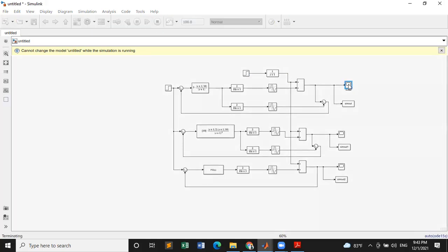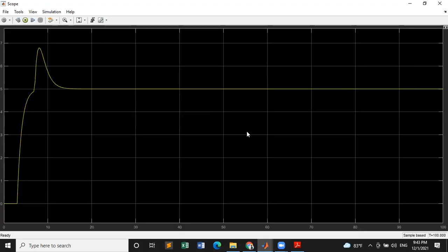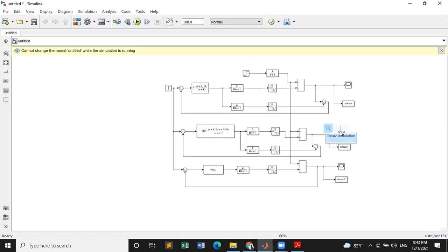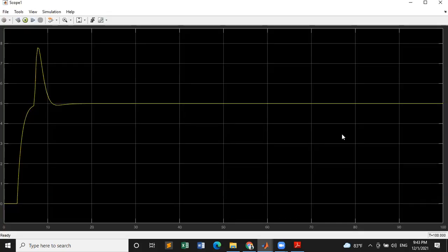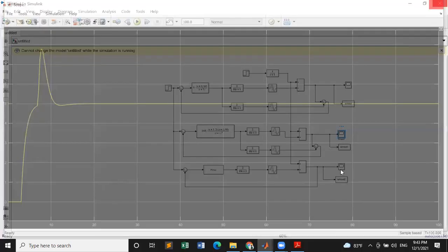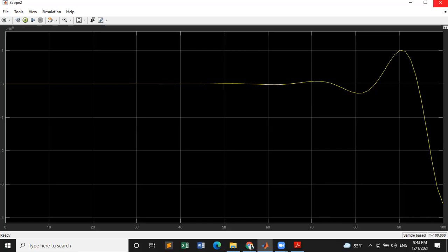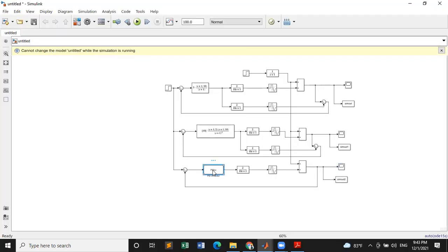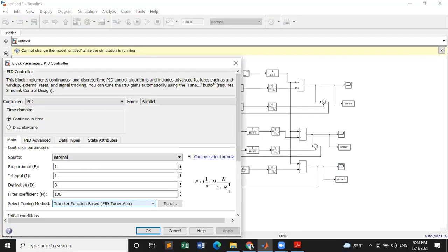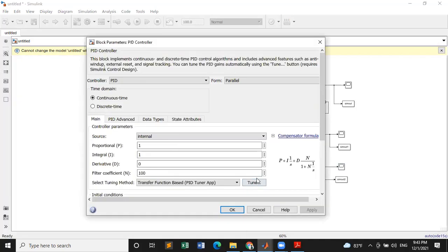Yep, we are getting some sort of a steady state. There's a delay. Then after some time we are getting a steady state without the approximation. Then with the approximation, I think we'll have to plot these in one graph and see how it's working, right? The general PID, we can tune this using the auto tune method like we did earlier.